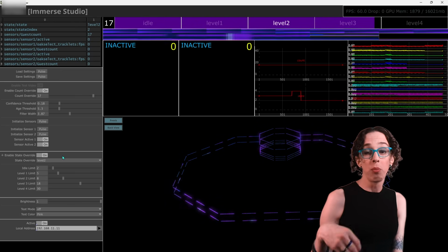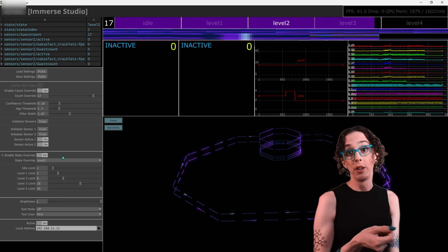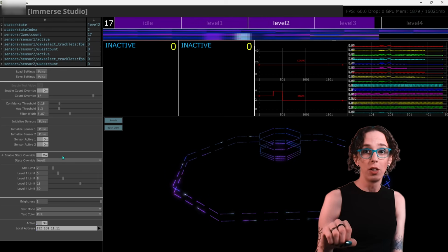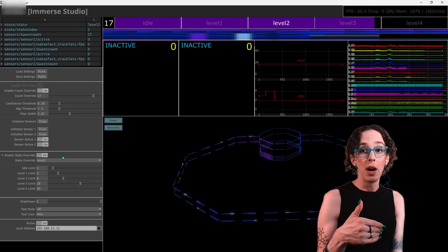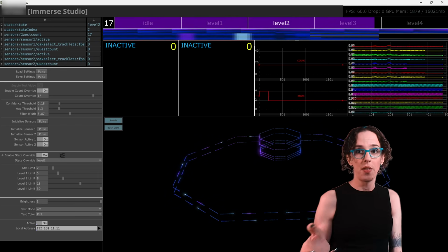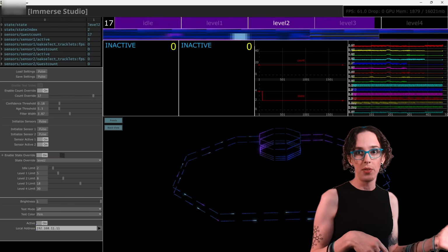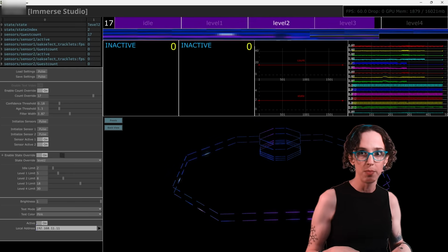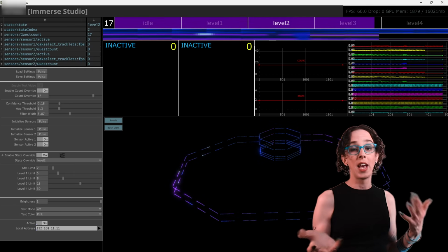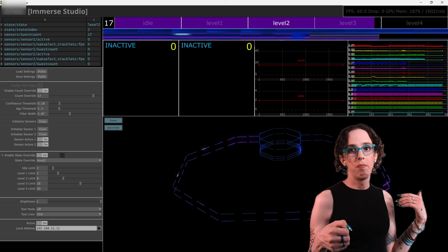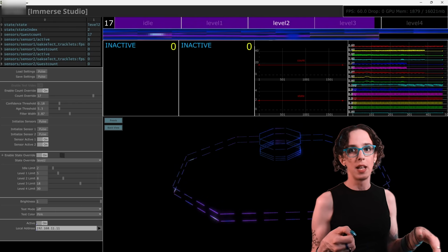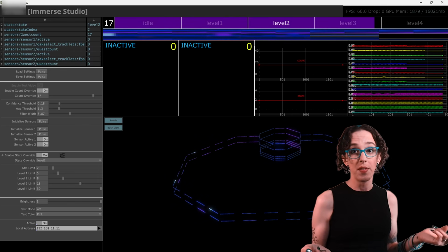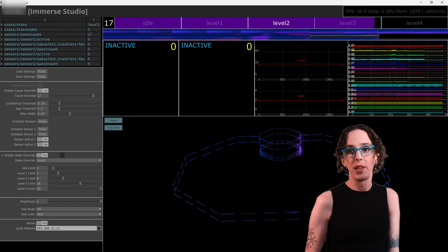One important thing related to those overrides is that during the startup process, which I'll get into in more detail later, it clears out those enable override settings so that it by default goes back to the sensors. That way, if somebody is sitting there testing things and then closes the project and reopens it, it doesn't stay in testing mode, because that could be something that an operator might not necessarily notice. And it could result in the installation just ignoring the actual sensor values.